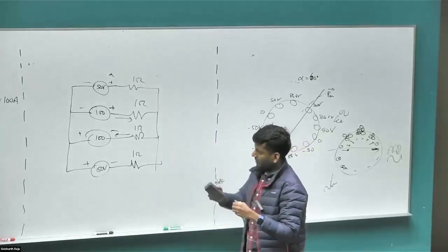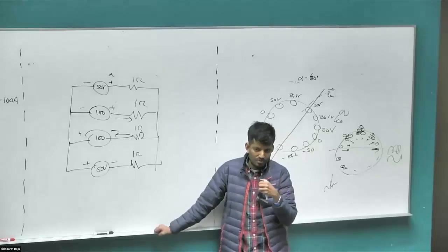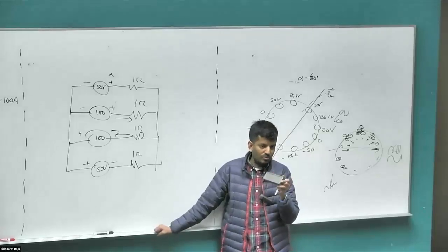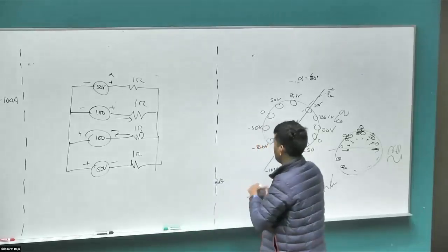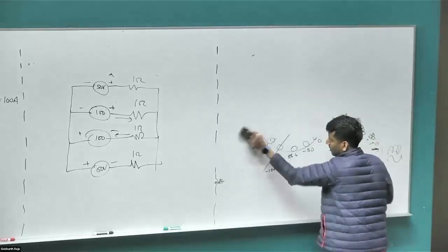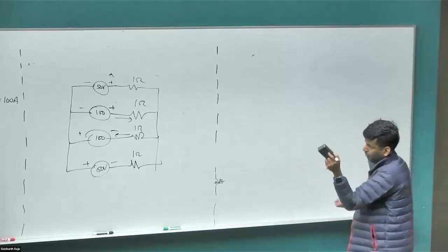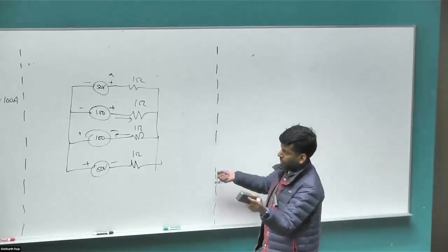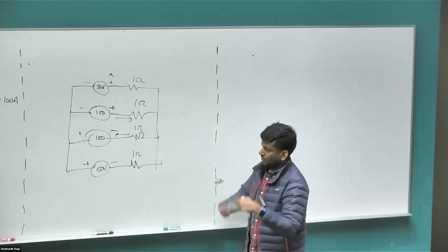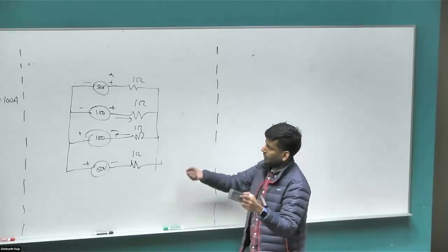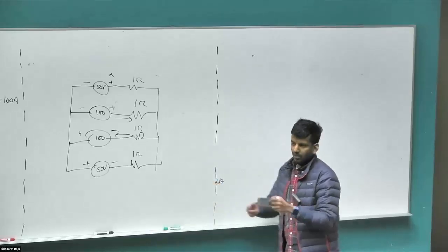How do I figure out what the currents are going to be now? So we can just apply superposition, right? It's all linear circuits here. What superposition says is that you can assume just one of the voltage sources is present, the rest are all shorted out, figure out what the current is, then do that for all the set of voltage sources. The current through any network would be the sum of all those currents, right?